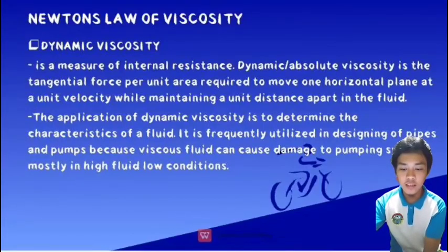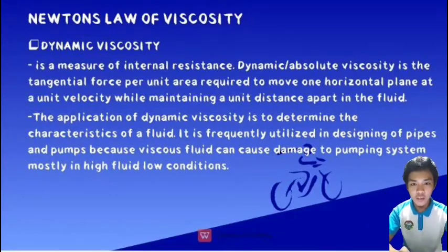Next topic to be discussed is Newton's law of viscosity. Dynamic viscosity is a measure of internal resistance. Dynamic or absolute viscosity is the tangential force per unit area required to move one horizontal plane at a unit velocity while maintaining a unit distance apart in the fluid. The application of dynamic viscosity is to determine the characteristics of a fluid. It is frequently utilized in designing of pipes and pumps because viscous fluids can cause damage to pumping system, mostly in high flow, low conditions.